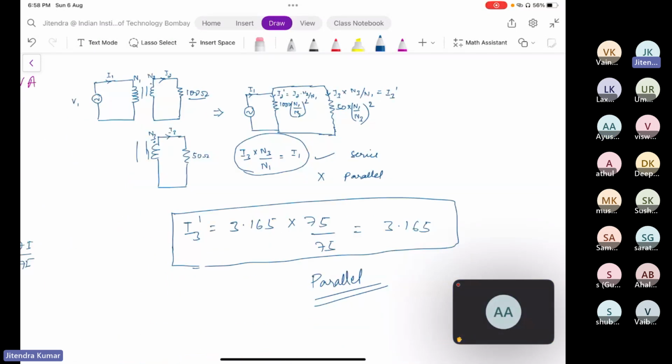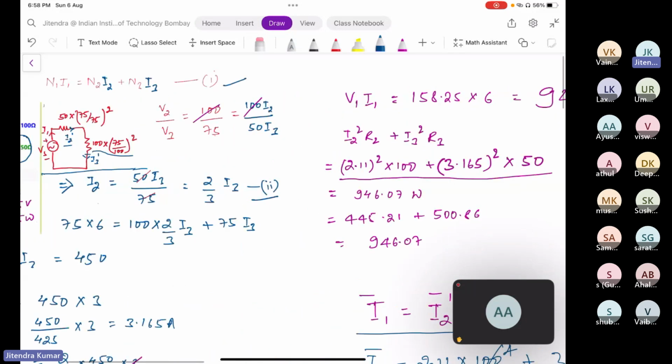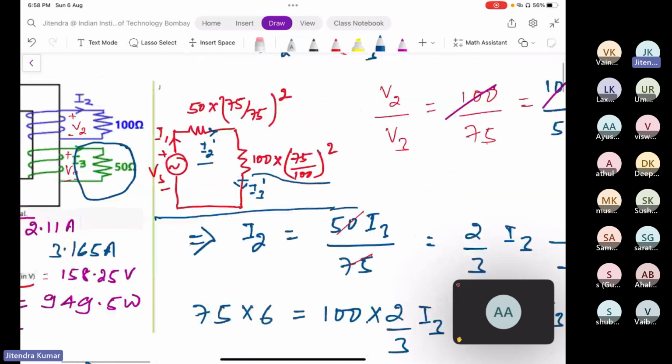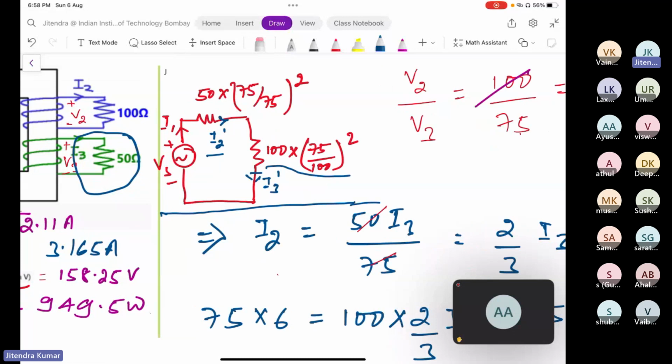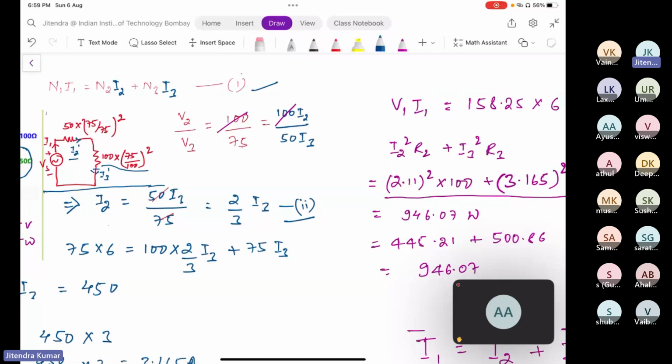Okay. See, so what I did is I connected both the windings and explored both possibilities, whether they will be able to connect in series or parallel. Initially we connected both the loads in series and we found some values. Some values are correct because of MMF balance. But the discussion led to whether we can connect them in series or not, or it should be in parallel.